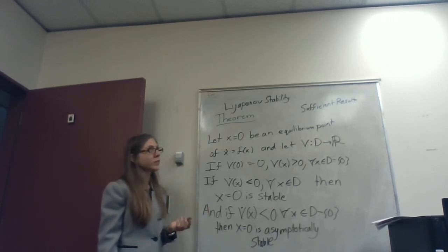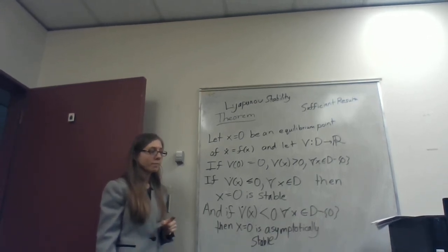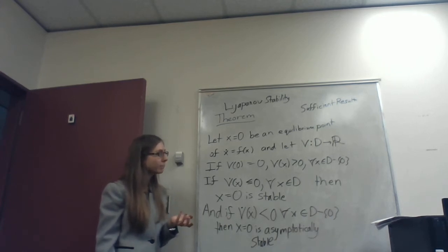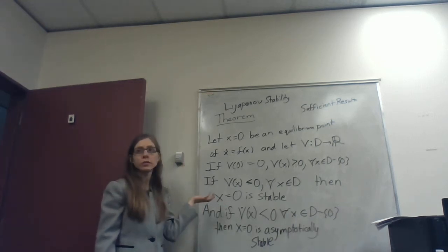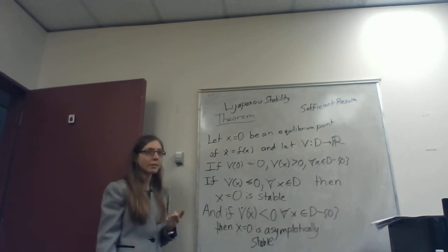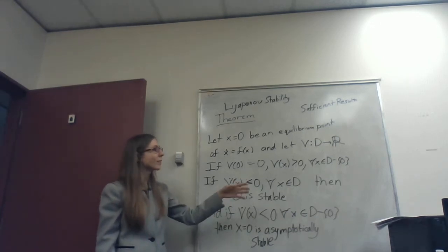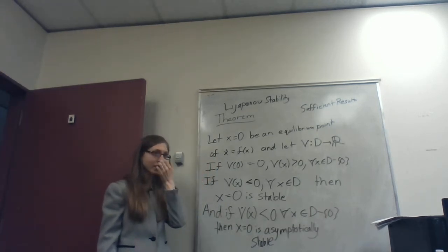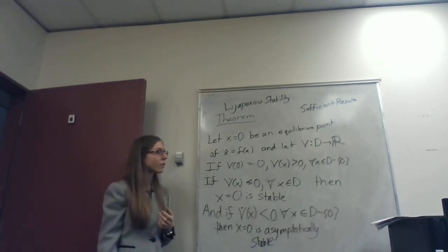This control design, we still work with that in our research group. It has benefits and disadvantages, and we're trying to see about overcoming some of the disadvantages over time. Benefits are, there's super rigorous proofs you can do in nonlinear systems that involve Lyapunov functions, so we can get really good provable properties for this controller under certain conditions. But the problem is these provable properties depend on being able to find certain functions, and it's not always easy to find those.